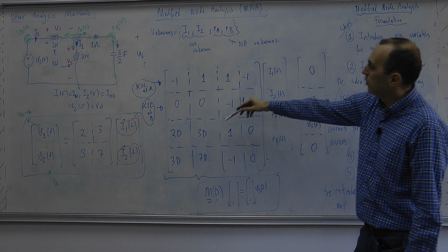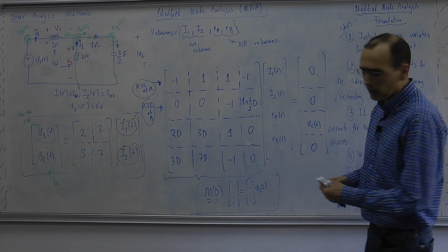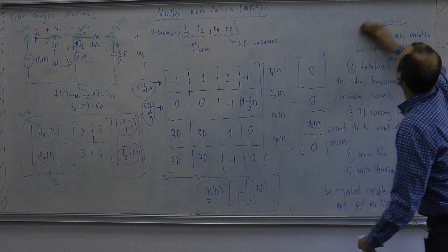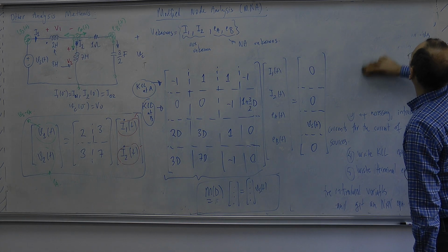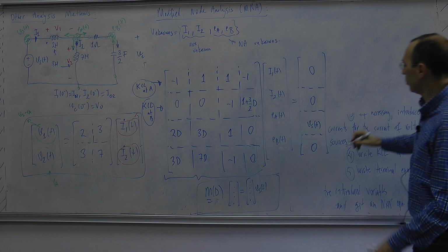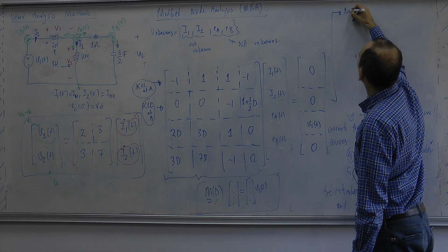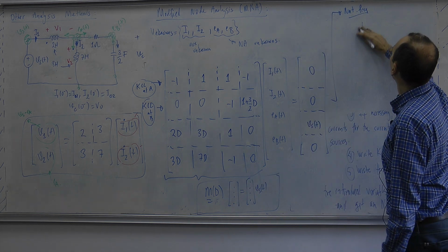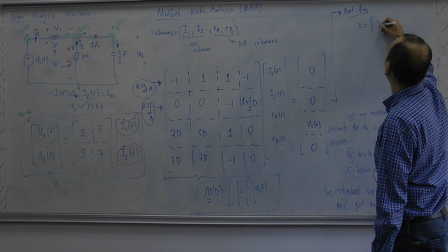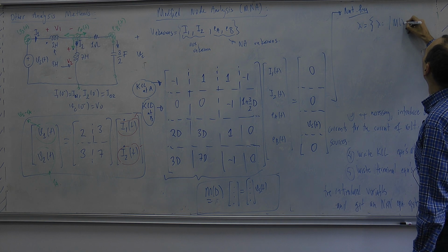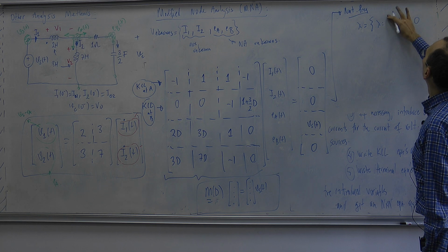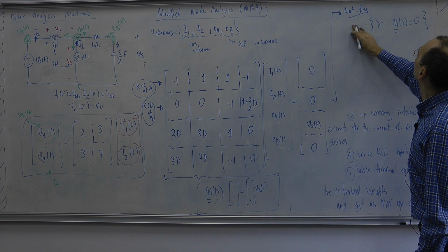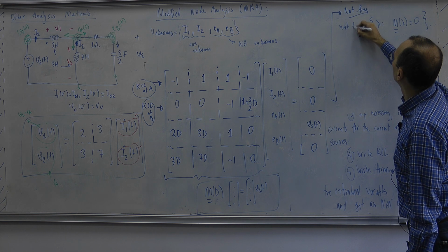But this makes our formulation of this circuit extremely easy. And since there is no D inverse operators involved, again, if you want to find the natural frequencies, well, I have discussed this already maybe third or the fourth time. The natural frequencies is this matrix lambda. Let's use a little bit of mathematics, such that this m lambda is equal to 0. Okay? So these are our natural frequencies.